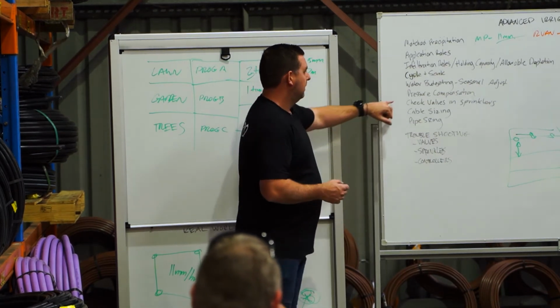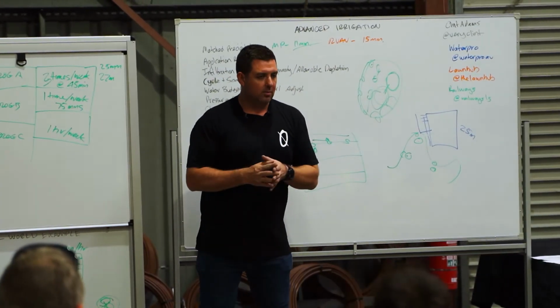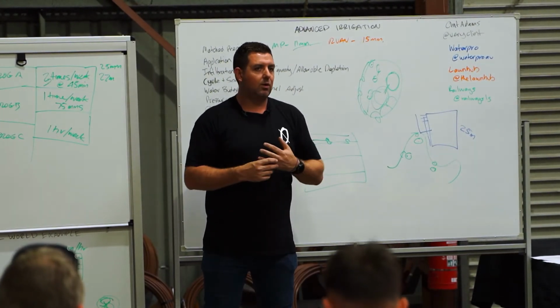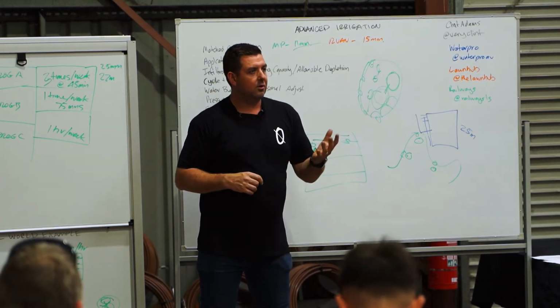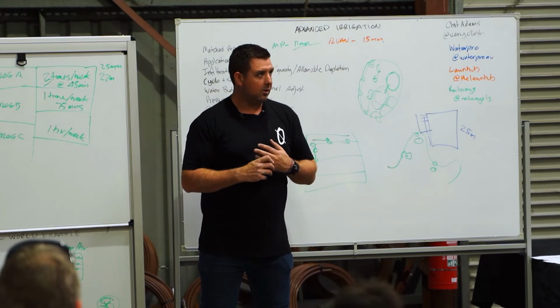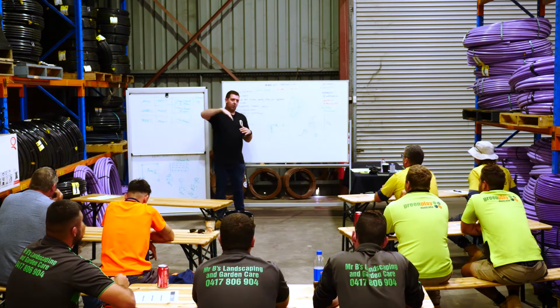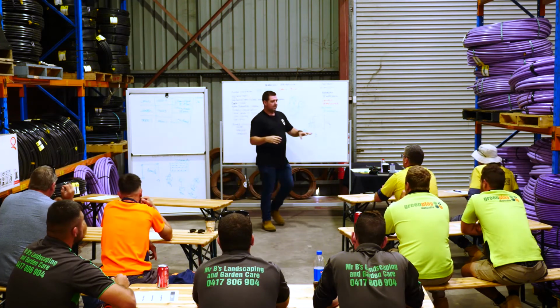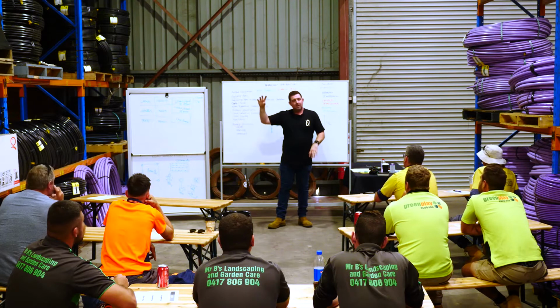Right, so pressure compensation or pressure regulation's been part of the drip tube environment for 30 or 40 years. Every roller drip tube that you're sitting next to now is pressure compensated. We do not stock non-pressure compensated drip tube. It ensures that, again, in those situations where you've got sloping areas, that the plant that's a meter below that plant gets delivered the same amount of water as the plant up there.